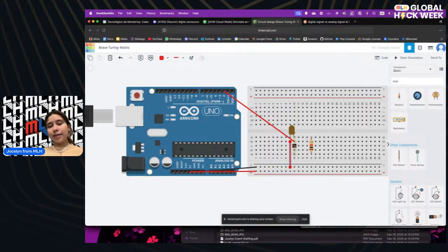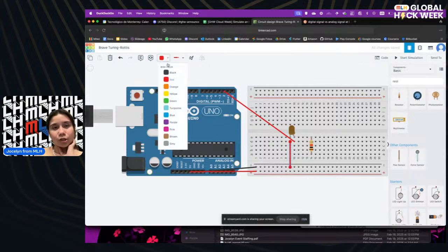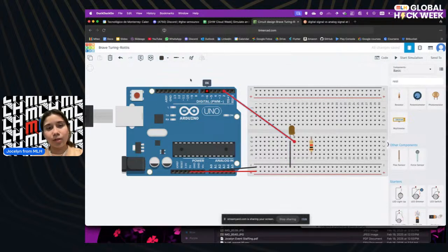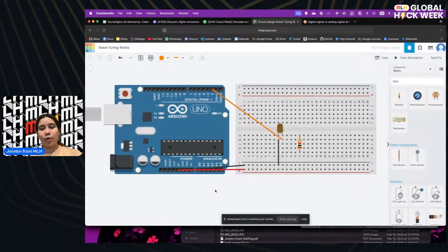I mean, I could directly connect this one into the negative over here, but as I'm trying to keep things a little bit tidier, you can do this, because if you remember, this line has power, so it will be connected. Great. So let me change this to black. And this one, let's change it to orange, because it's the LED one. Right now we don't have any resistor in here, so when I turn it on, it will very probably burn.